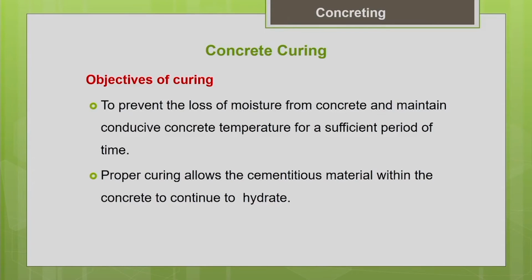Okay, the next important step in concrete making is curing of concrete. Okay. So far we discussed consolidation of the concrete and finishing of concrete. Okay. So now we are going to discuss the curing of concrete. So why is this curing needed? So as everyone knows, the cement hydration is a continuous process.